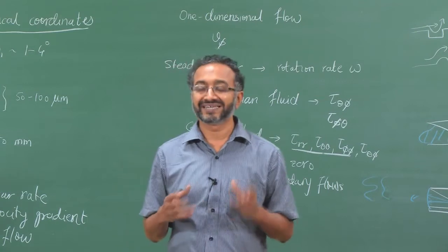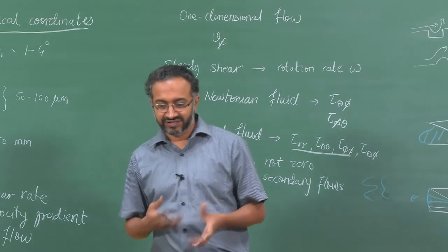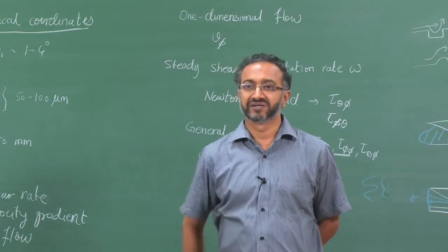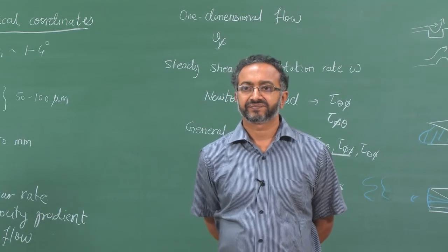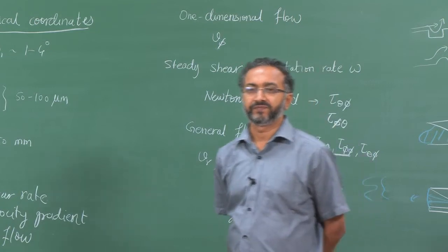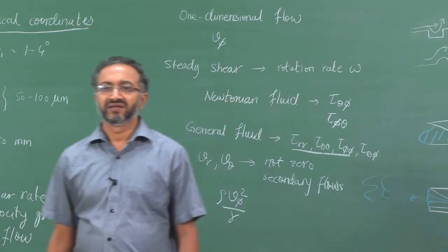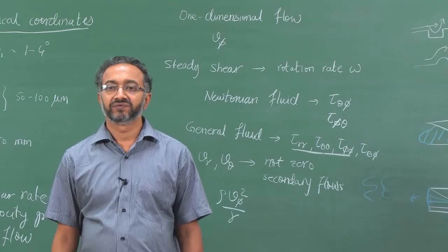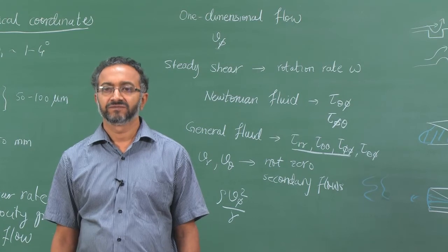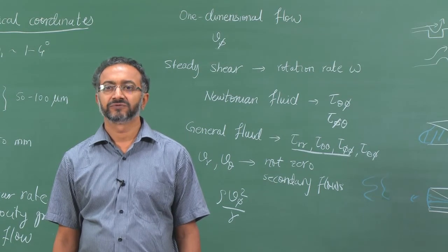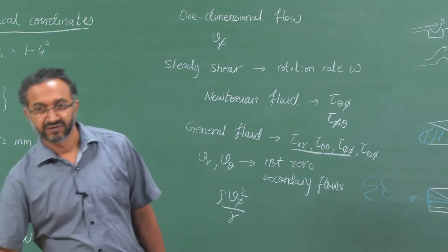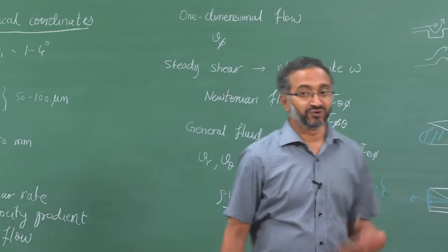So, how do I examine whether the one dimensional flow assumption was indeed valid during the operation? If we do various speeds and we see how the viscosity behaves, if it is a constant in a particular zone, then we can assume that secondary flow is less. But suppose we are increasing from a very small velocity to a higher velocity, definitely if we plot the viscosity, when the turbulence or secondary flow comes into the picture, we can see the deviation of viscosity. Yeah, but we do not generally know the viscosity, right.